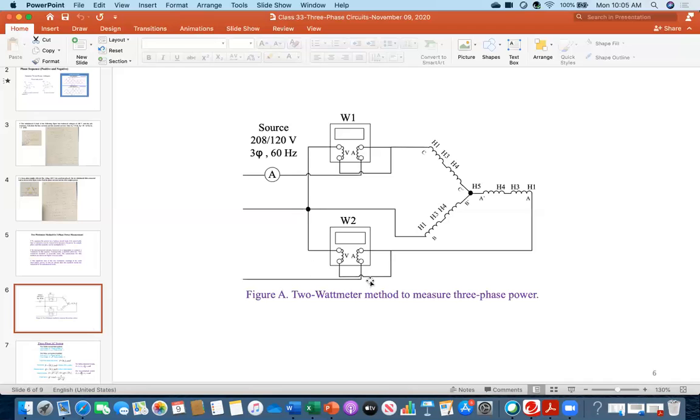And then a pretty interesting thing, you see, you have another wattmeter. Again, you are connecting the current coil in series with this phase. And then the line is going. But then look, the voltage coil, one end you are connecting with this phase, for which you are measuring the voltage. But then the other end of the voltmeter is connected here. So this means that these 2 wattmeters are taking into account all 3 coils, because you see this one, this is a common point. That's why automatically, inherently, it is taking into account all three phases.